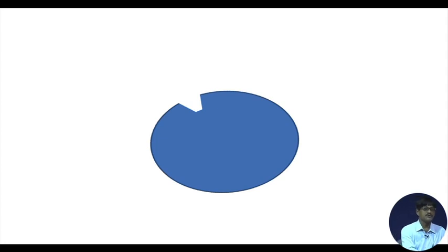So, after this, the second tooth space is taken up by the cutter, that is it. So, it will again move to and fro and cut off one tooth space like this. So, this thing goes on getting repeated again and again, so that all the teeth on the periphery of the gear, I mean tooth spaces, they are cut off, and you have a gear properly made.